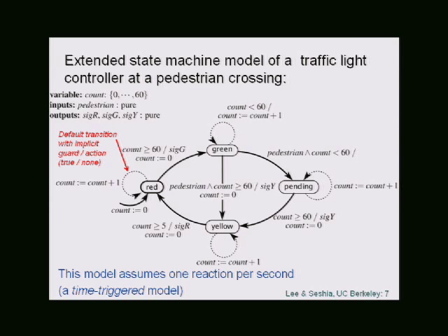Now, this is one of the tricky things with modeling with state machines, because we assume that these edges are instantaneous. So if there's code running which will take a certain amount of time, it's best to model that as a state. And then you will have to model the occurrence of an interrupt as a different state machine that runs concurrently with the original state machine. As we'll see in the next lecture, you have to compose these two state machines. And then when you compose them, you will see all possible behaviors, including the behavior you've described, which is you're running a piece of code, and then you get interrupted in between. You'll have to follow that path in the combined state machine to see what happens.